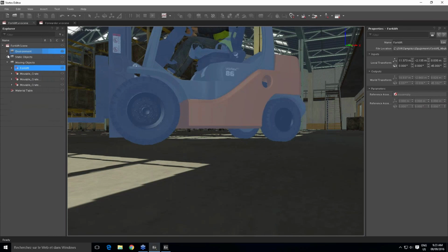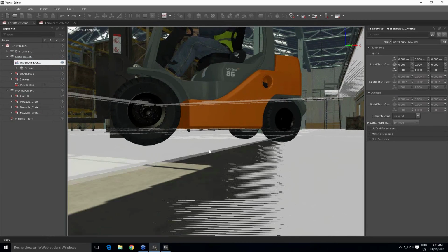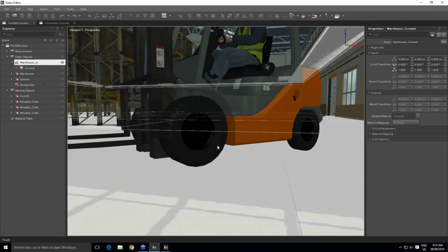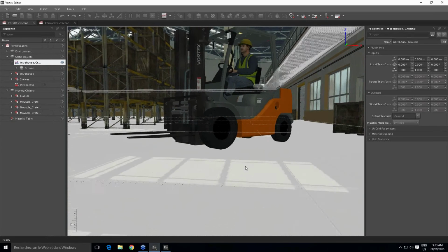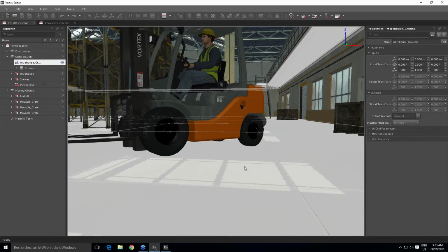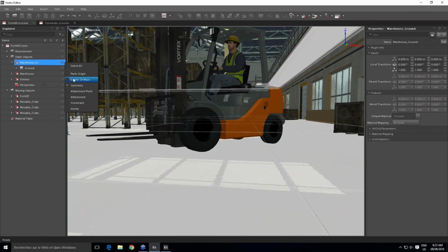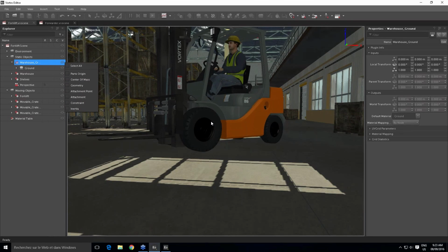I'm going to go back into Static Object, and this time we're going to check out the ground itself. So the ground looks fine, but oh, wait a second. What's this? There's sort of a line there. And it seems that, yep, that's where we get our bump. Okay, so at least now we have a direction where we can go. So we're going to turn off the geometry again.